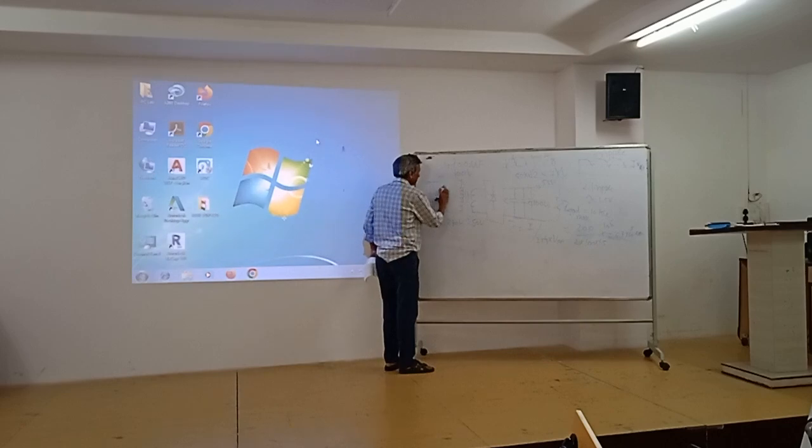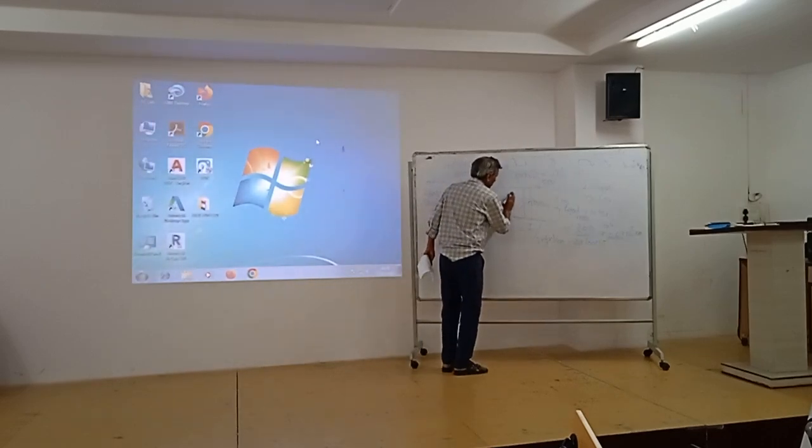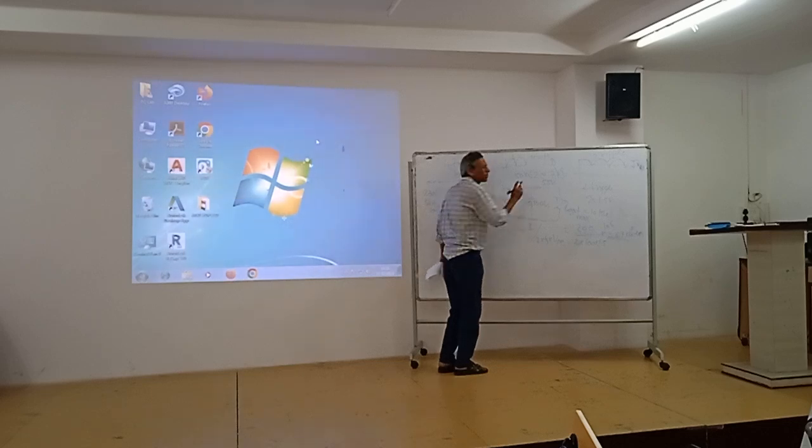There are multiple ways. One way is that I will put a, let me put it in secondary only. I will remove this capacitor. I will put a series resistor of few watts, say 10 ohm, 50 watt or whatever, something.